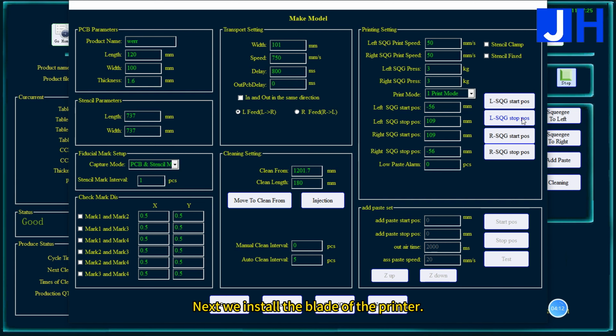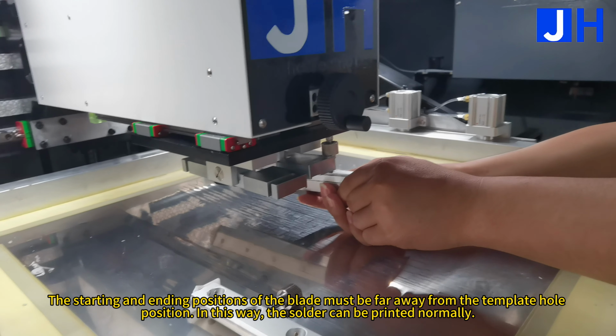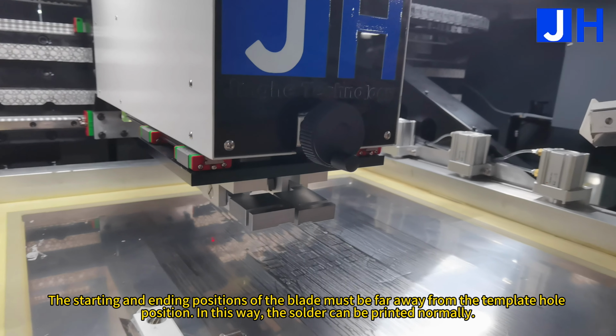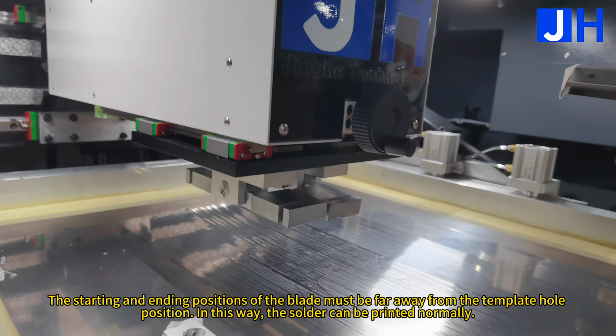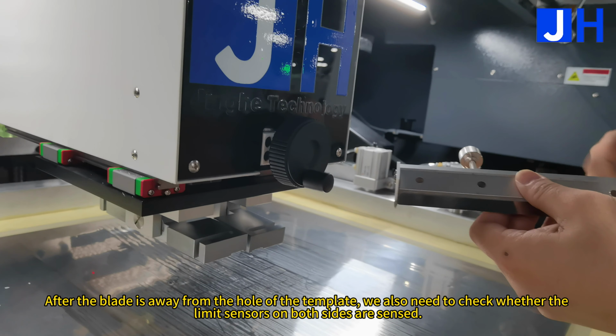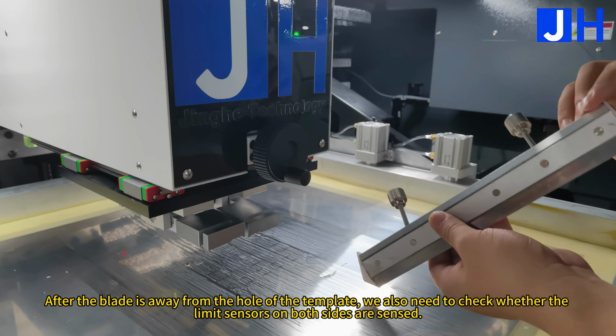Next we install the blades of the printer. The starting and ending positions of the blade must be far away from the template hole position. In this way, the solder can be printed normally. After the blade is away from the hole of the template, we also need to check whether the limit sensors on both sides are sensed.